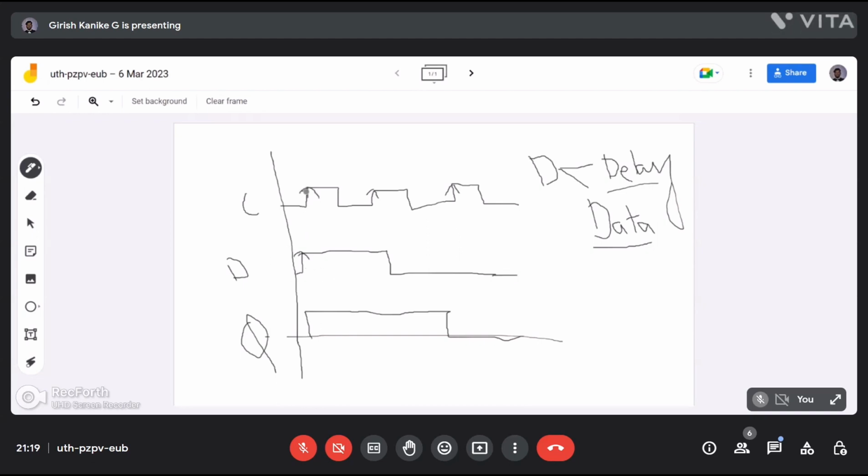So whatever input you have at this positive edge, the output comes from the past input. At this positive edge, the D is 1, but you won't get it at the immediate clock edge. It will be outputted at the second clock edge.